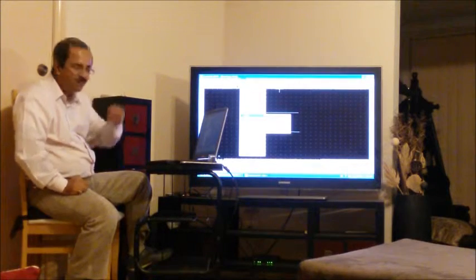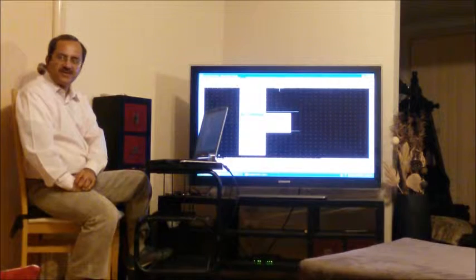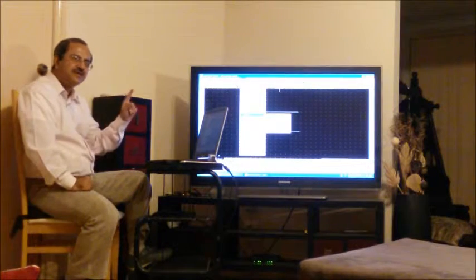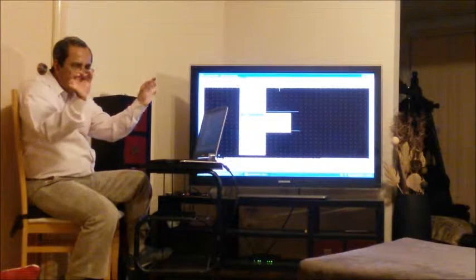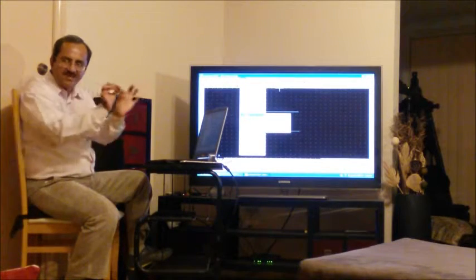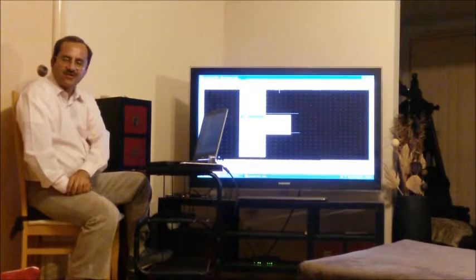And there is another one, 2 point. Usually you can't draw the circle by using 2 points. But there is a special feature in AutoCAD that if you give the 2 extreme points which are on the diameter, then still you can draw the circle.